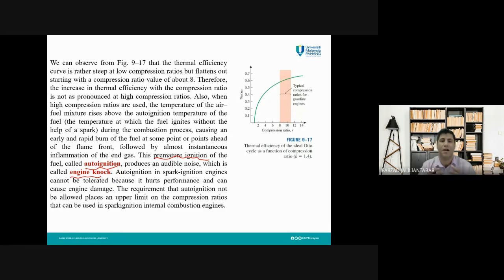As I said, ignition starts simultaneously because of the high compression and temperature, and this ignition happens in different places in the cylinder. It does not start from just one point and then expand to the whole cylinder and push the piston downward. It just starts in different places, and these different combustion regions may cause different sources of energy.